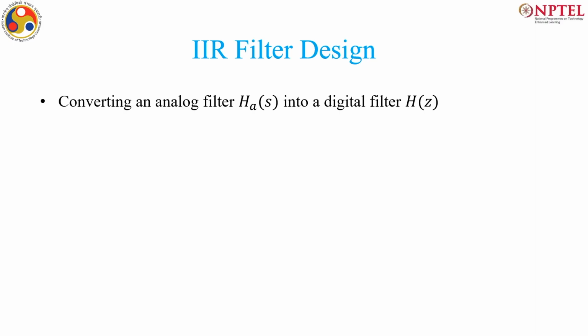So, we will quickly now go to the IIR filter design. Here the catch is that in an FIR filter we know exactly how many values of h[n] we require, but in IIR we do not know, because there is an infinite number of points of h[n]. So, naturally it would be foolish if I try to design all the infinite values of h[n], right? In the difference equation also, do we write infinitely many terms for x[n]?